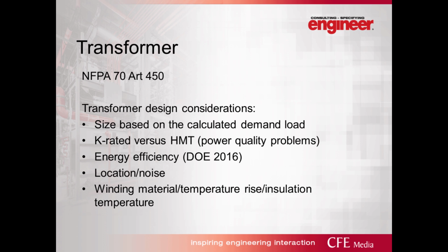When there is a power quality problem or the project has a lot of nonlinear loads, such as computers or servers with switch mode power supplies, motors, or variable frequency drives, the engineer may recommend a harmonic mitigating transformer or a higher rated K-rated transformer.